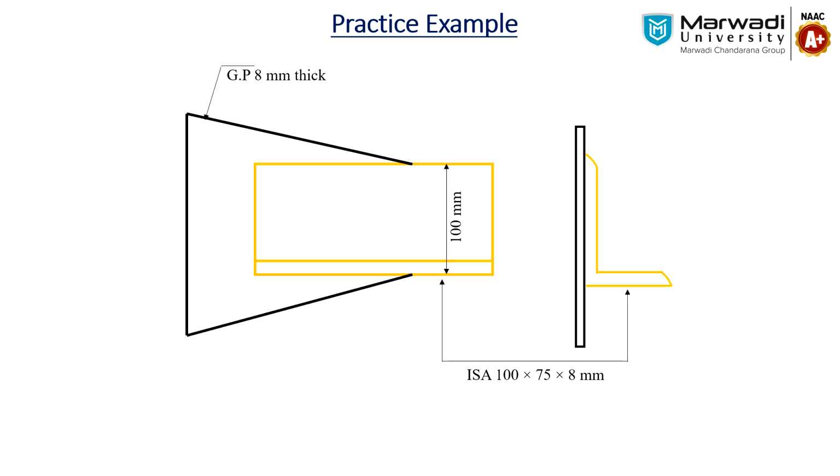this is a tentative type of the connection. When we discussed the plate, as it is a rectangular plate, CG will be at the center only. So when we have to weld on the sides, on the top and bottom or toe and heel, both sides will have similar length, because the CG will be at the center. But in the angle section, CG will not be at the center.